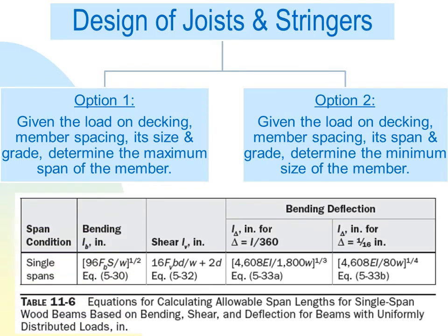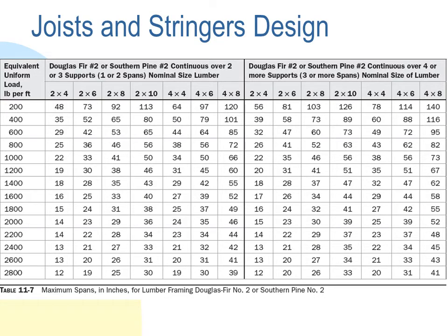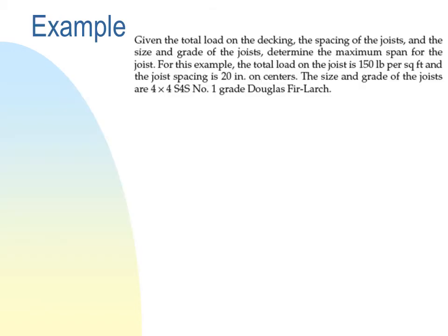And again you have the 4 deflection criteria, the same 4 deflection criteria. However, now the equations will differ, again depending on the number of spans that we are talking about. And again, somebody did the homework for you, he gave you these tables, so once you know your load and you know the sizing, you will get the maximum span. And again here you need to recheck the deflection.